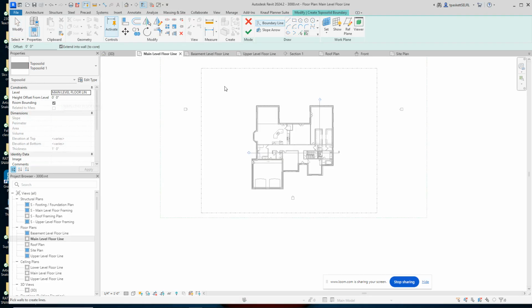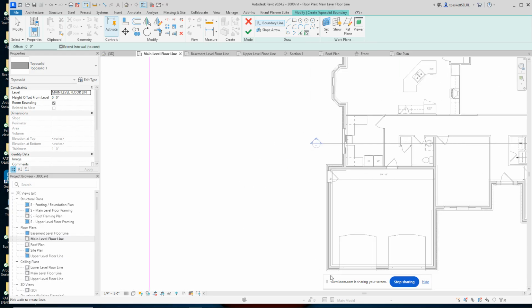And all we need to do at this point is I want you to go around and do Select Lines. And you pick the property lines. Just select each of the property lines. And then you go in and we're going to do a perimeter around the house. So now go to Select Walls and work your way around. Again, one click per side, so you don't want to overdo it.